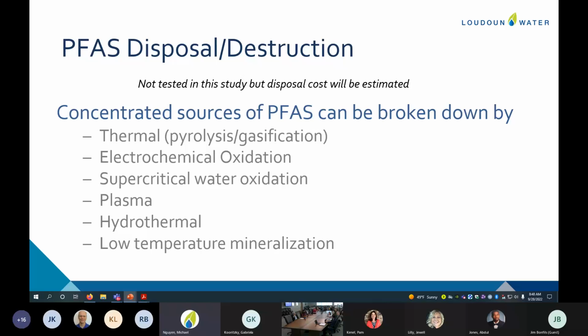So it's not dilute, it's not in a waste stream, and they applied some solvents. It seems to work on some types of PFAS, but the sulfonic acid family, it doesn't work on. Of the 24 PFAS we normally measure, sulfonic acids are about 10 of them. So it might be a potential to destroy maybe half of the PFAS family we're looking at.